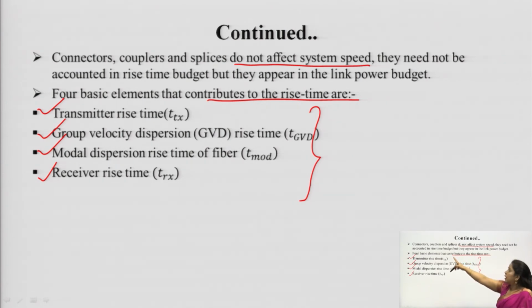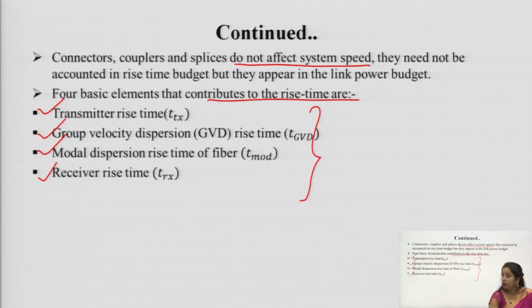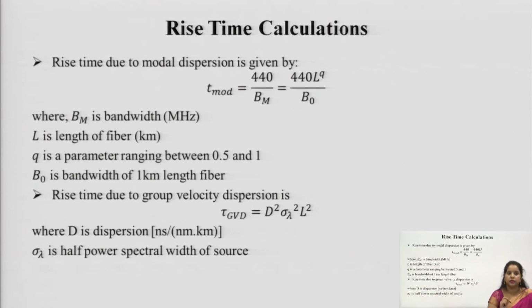Always remember, couplers, connectors, and splices do not contribute to the rise time, they only contribute to the power loss. Now, one by one we will discuss the other parameters, the various contributors to the rise time, and how much each contributes to the rise time.